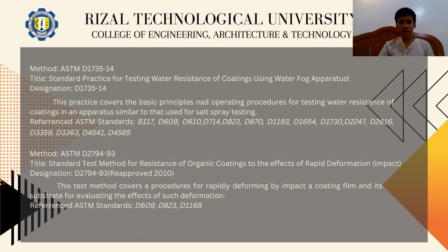Water can cause the degradation of coatings, so knowledge of how a coating resists water is helpful in predicting its service life. Failure in water fog tests may be caused by a number of factors, including a deficiency in the coating itself, contamination of the substrate, or inadequate surface preparation. The test is therefore useful for evaluating coatings alone or complete coating systems.